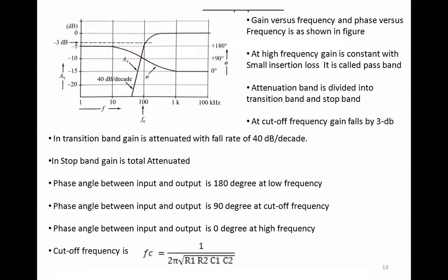And now we are looking at the same graph here, but the fall off rate has actually slightly increased. So it's at about 40 dB, right? And you can see it's 180 plus 180, 90, 0. Why plus 180? Because it is going here, so there's a shift happening. Let me just draw that, right? So there's a shift happening in this way. So there's a 180 degree shift. So keep that in mind.